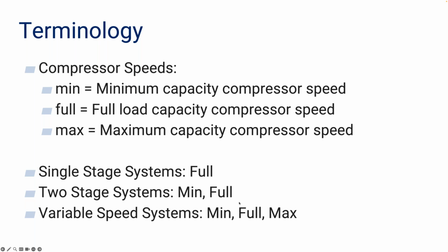I think a lot of people aren't familiar with this, but for variable speed systems, the manufacturer can more or less select which speed they want to use for their full load rating. It doesn't have to be the maximum. It often is, but it doesn't have to be. There are various reasons why you might want to go one way or the other. Basically, it's a trade-off of capacity and efficiency, which speed you choose. This is the terminology we're going to use, and it does get muddled up a bit. Sometimes they'll say rated capacity instead of full load. So hopefully that's not too confusing.